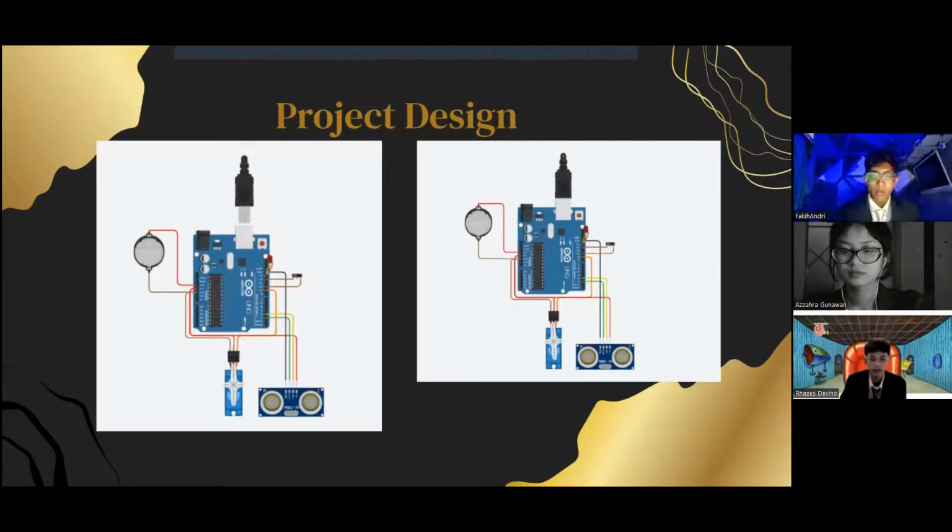And then there is the LED, with the cathode connected to ground and the anode connected to the resistor so that the brightness level of the lamp can be adjusted. And there is a switch so that we can set the program on and off. We connect terminal 1 to digital 12 and terminal 2 to digital 10.